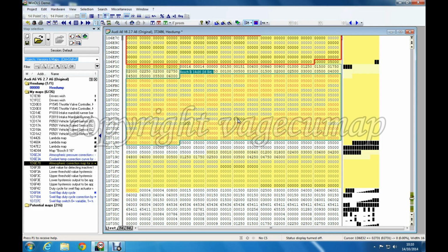That is why I suggest that if you're going to do something like this, you strip out the manifold, strip out all the bits that you don't want, put everything back together without the flaps, then change the maps like this, and then finally delete any codes that are causing any problems, and then after that no more flaps to worry about.